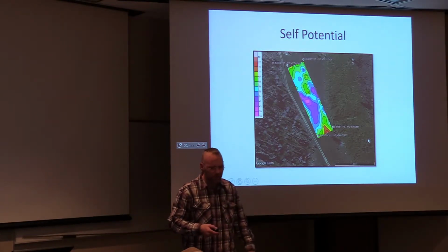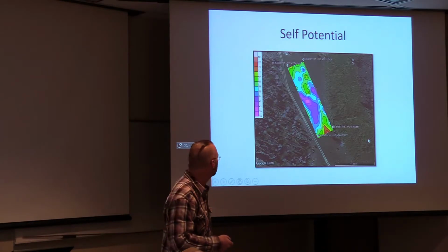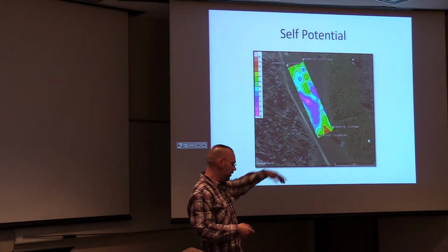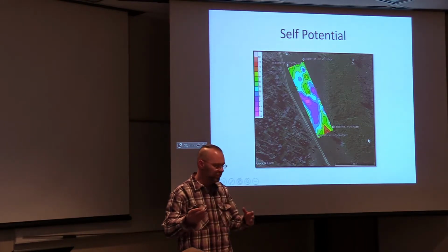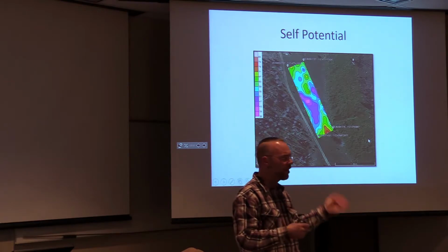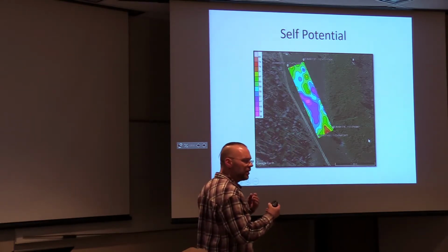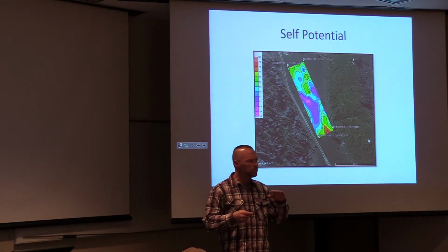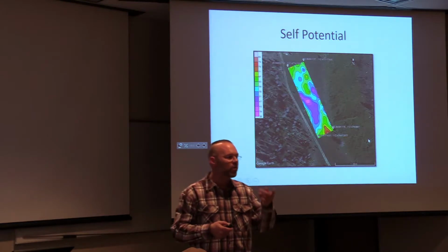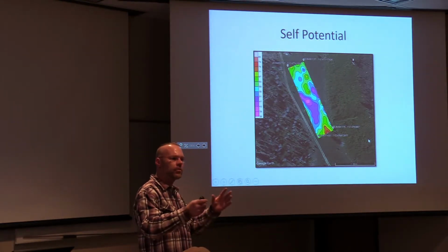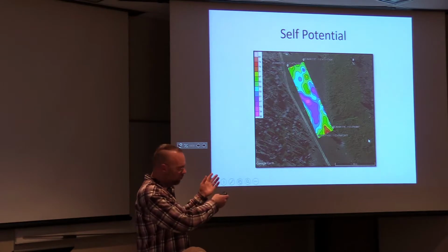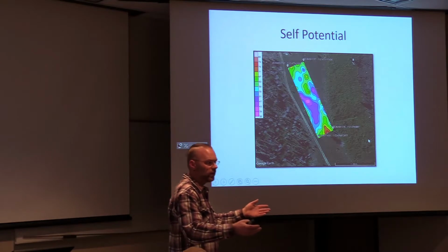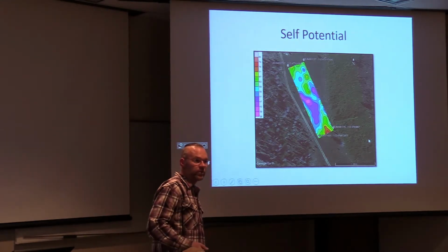This is a method called self-potential, SP, sorry, I got it wrong. He has this big cable that he induces a current, and I don't remember if he goes from positive to negative or negative to positive, but he can detect upward or downward movement of water. He can detect basically the flow of water. And one of the cool things, hydrogeologists always talk about the heterogeneity of the soil. Well, we didn't see tons of it in the actual alluvium. We see sandy, silty stuff, and resistivity shows that.